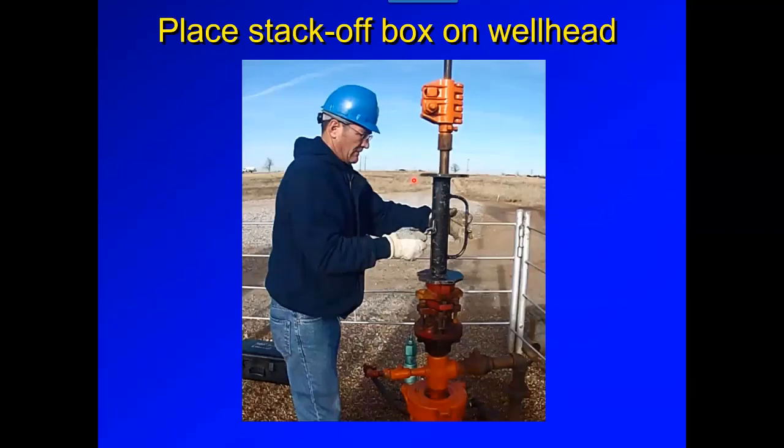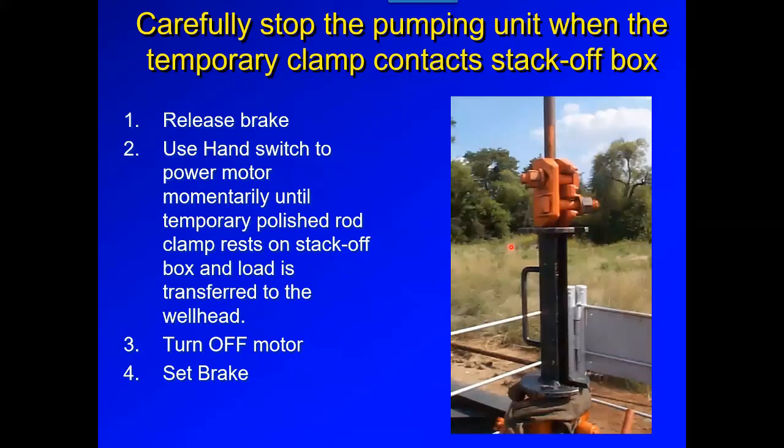We're going to reinstall the stack off tool. As you can see, Mr. Ken here is installing the stack off tool, as well as utilizing the chain, making sure that we have it chained in position. We're going to release the brake and momentarily turn on the pumping unit, allowing the stack off tool to hold the weight of the rod string and creating separation between the carrier bar and the rod clamp.